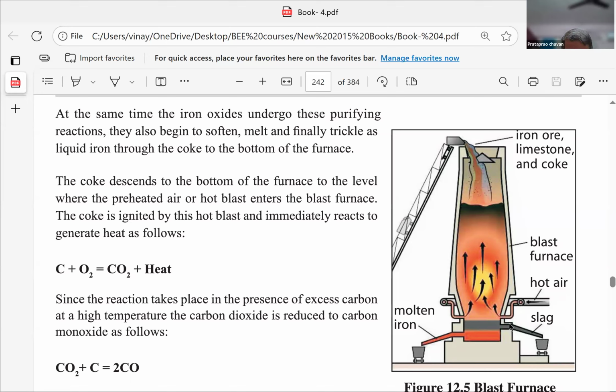So these are drained out separately. This is a slag trolley. If you visit any blast furnace plant, you will find a separate slag trolley. It removes slag regularly. Once they open this door, the slag will come out. Then once the slag is removed, what remains here is the pure metal, iron. That is removed into another trolley, the metal trolley.